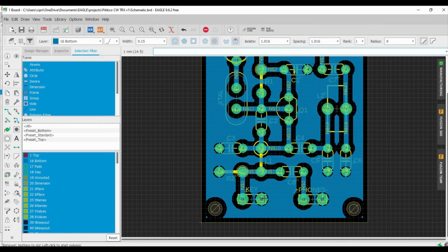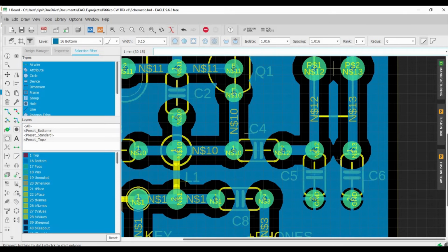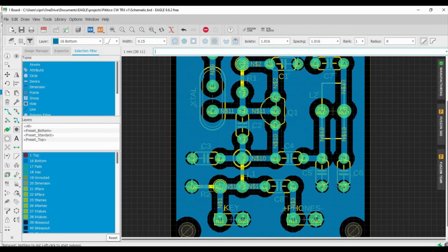Of course, I'm going to double check to make sure that there's continuity between each ground connection to all the components. Sometimes if I have a schematic with a lot of components, especially because of the distance that I'm using between the traces and the ground connection, I might miss a ground connection and one of the components might be in air.